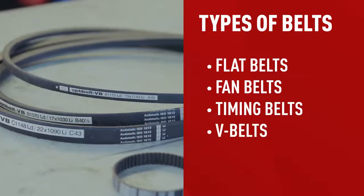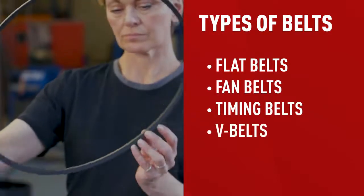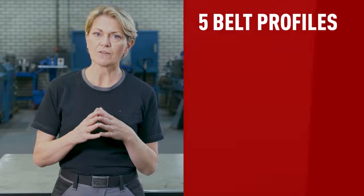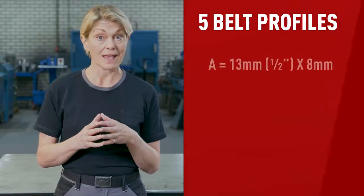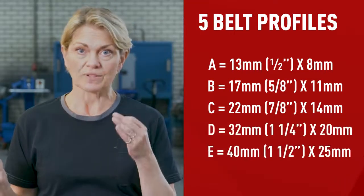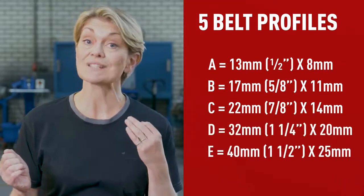V-belts are by far the most common, since they're widely used in many different applications. They are easy to install, don't require any lubrication, and V-belts offer a slip-resistant and high-speed power solution. Classical V-belts come in 5 profile sizes: A, B, C, D, and E, and the top width and depth dimensions are to an industry standard.